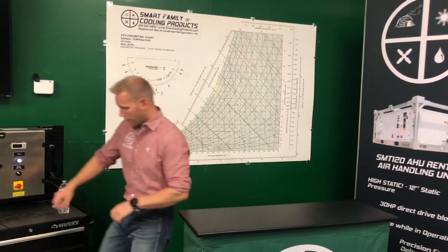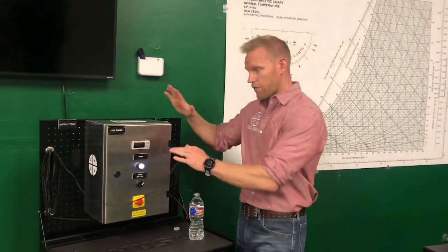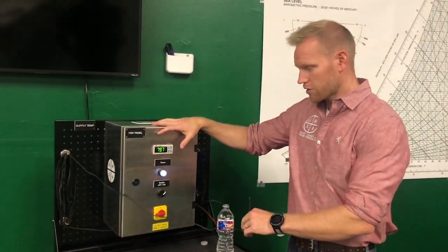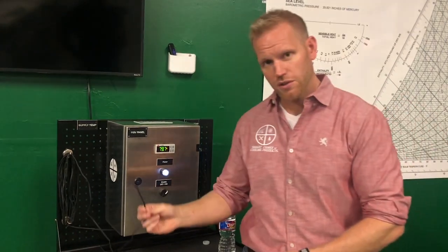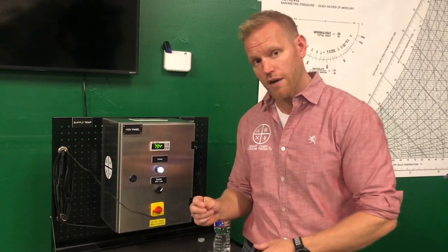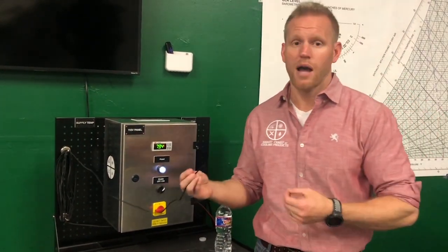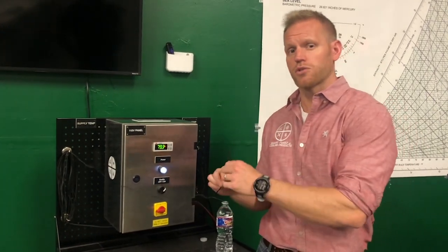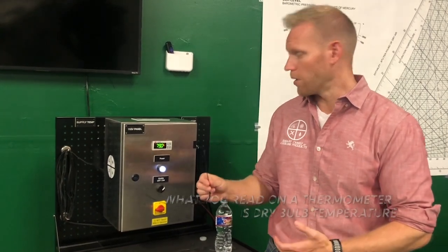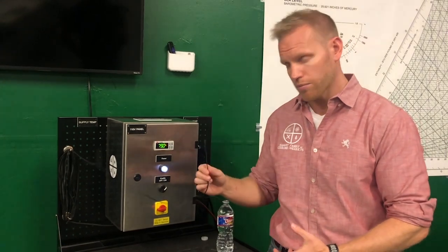So I happen to have a temperature sensor here. This is used on one of our Smart Family training modules here. We have a little controller that we use on our air conditioning units. So this is measuring temperature. And the temperature in this space is 79.5 degrees in Fahrenheit scale. And we would actually say that that's the dry bulb temperature. Normally when we're talking in groups of people and we say the temperature in the scale, we're talking about dry bulb. So this air is currently 79 degrees Fahrenheit, dry bulb temperature.